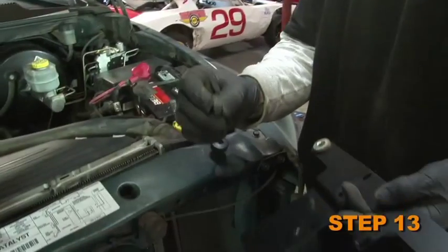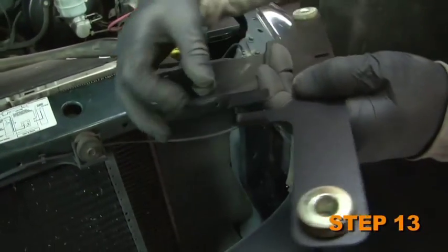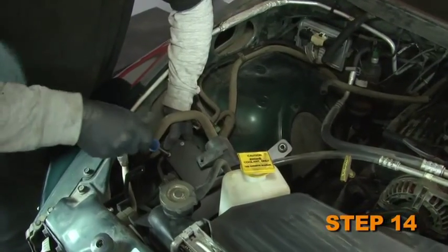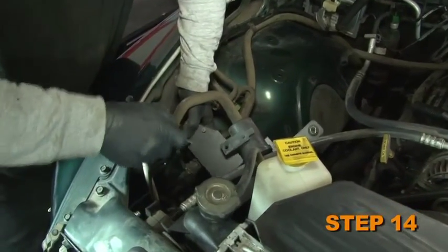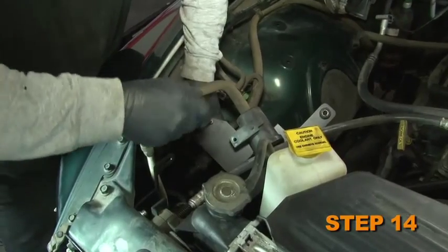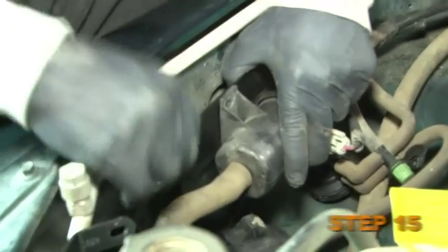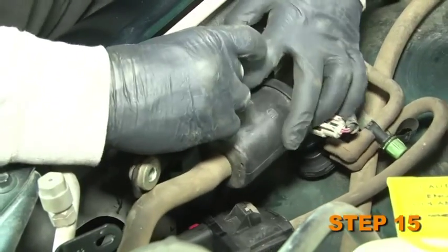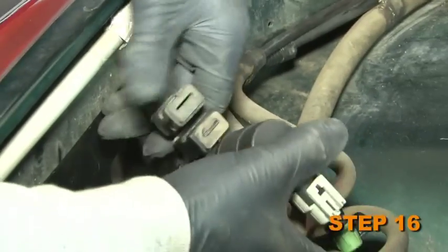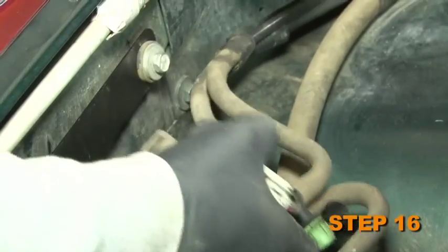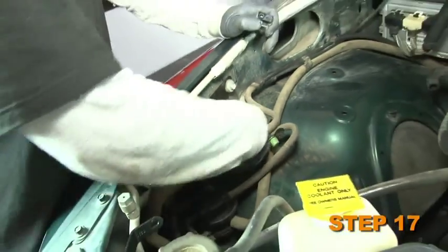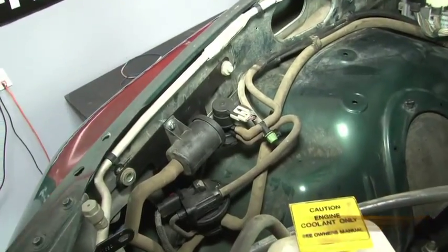Install the provided step bushing into the hole on the back side of the evap assembly bracket. Install the evap canister onto the evap assembly bracket using the original screws removed in step 10. Install the evap canister vent onto the evap assembly bracket using the hardware provided. Remove the rubber-mounted locating bracket from the purge control solenoid. Install the purge control solenoid onto the evap assembly bracket.